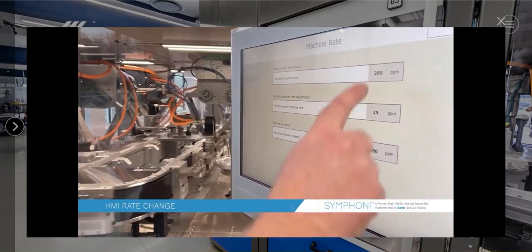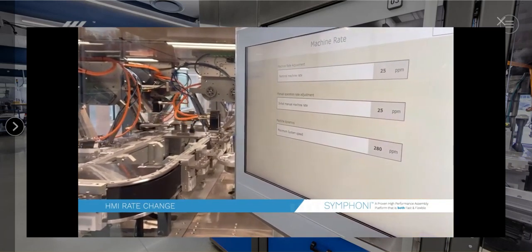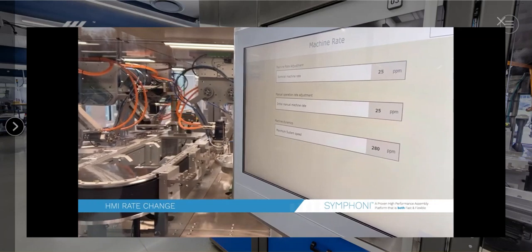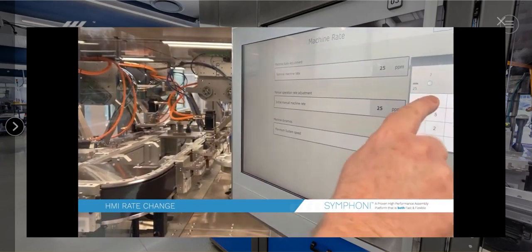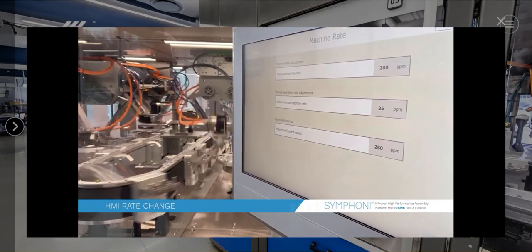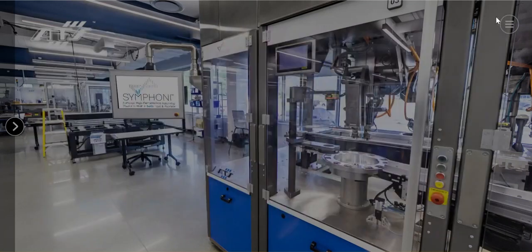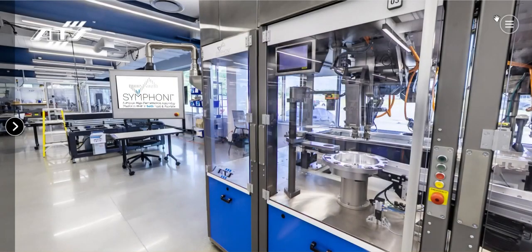So regardless of what rate the machine is running, all of the motions are coordinated together in the same fashion. This can be a very useful and helpful thing if you've got something going on in the machine, maybe an intermittent issue that's occurring, and you can't really see what's going on with normal high-speed operation. You can go over to the HMI. You can reduce it down to half speed, a quarter speed. You can take it down to 1 part per minute and actually get in and see what's going on and use that as a troubleshooting aid.